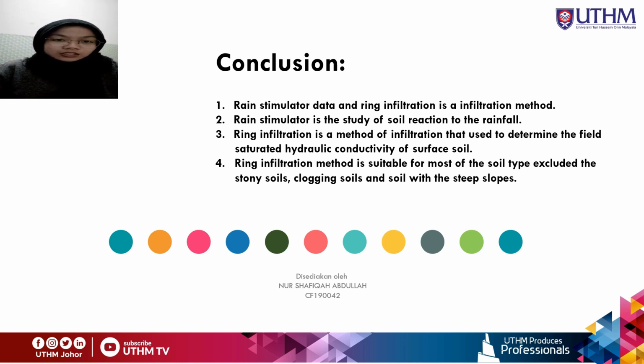And the ring infiltrometer is a method used to determine the field-saturated hydraulic conductivities of a surface soil. The ring infiltrometer method is suitable for almost all types of soil, excluding stony soil, clogging soil, and soil with a steep slope.